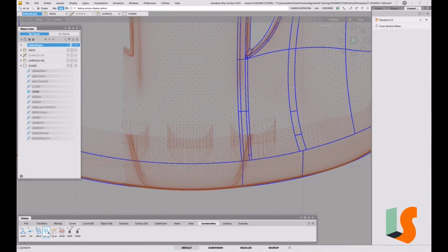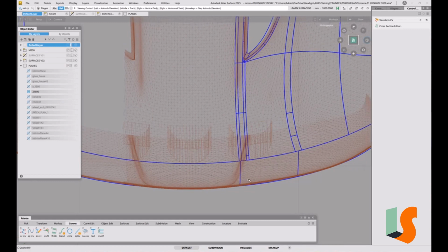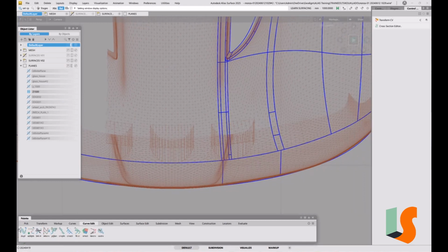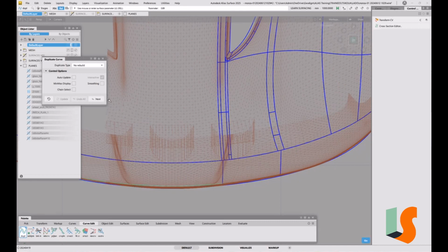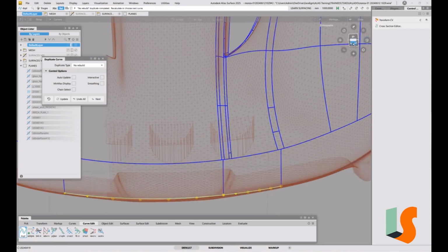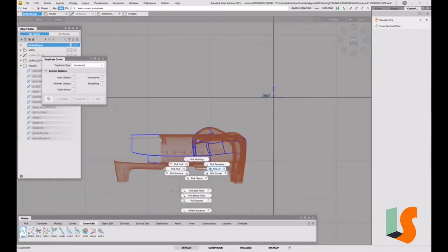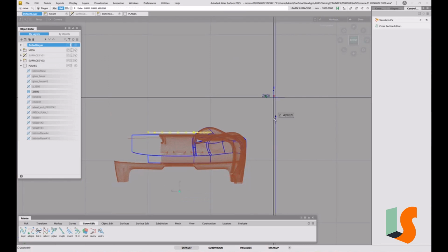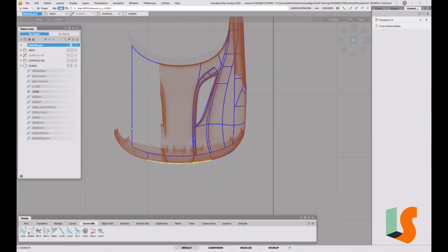And so we'll put a curve in here. Well, actually, I'm going to take this edge here and duplicate that first of all. So in fact, it's not above the geometry when I do that. And once again, as always, I need to switch off interactive, so I just get the edges there. So I'm going to pick those two curves there. They are absolutely on the edge. So really I should just, for tidiness, bring that up and use Alt with the right mouse button to snap them onto that Z value so that they're above the geometry.